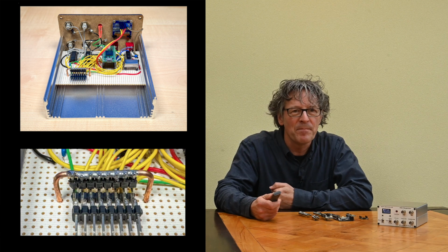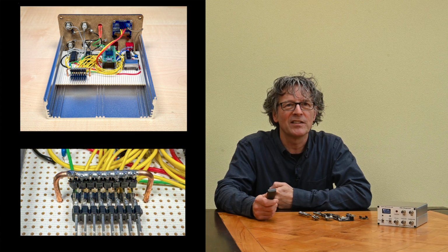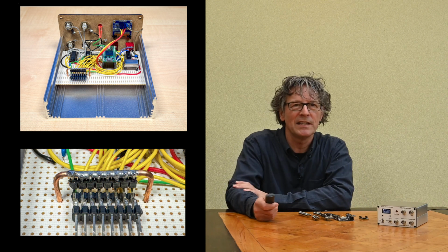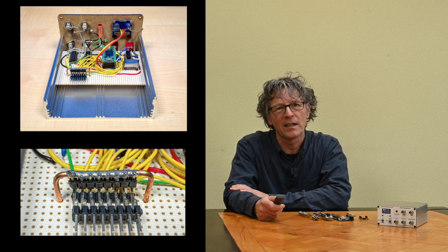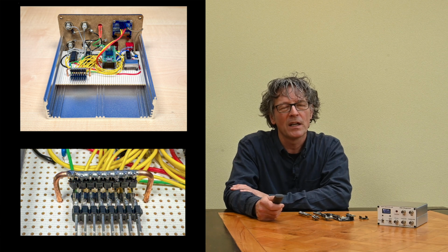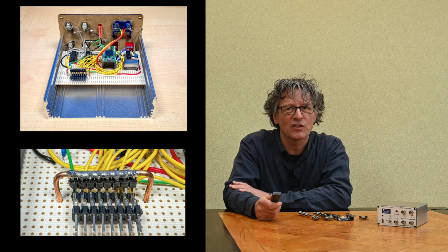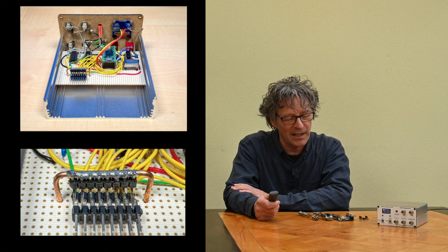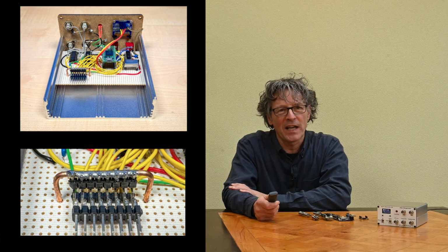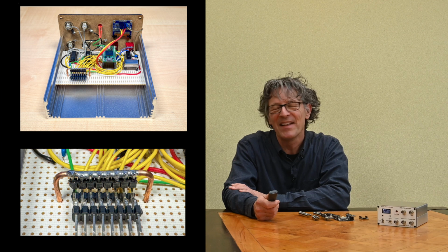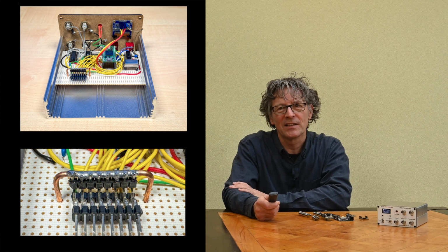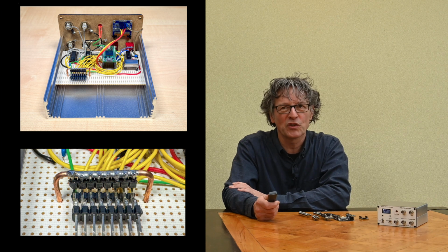Let's make it a little bit bigger here. That additional header is a debug header. It can be used to connect the prototype right away to the digital lines of a digital oscilloscope, to do some further analysis of how the code is running internally. The reason why I built a connector like this, I mean, it's a bit brutal, is that I wanted it to be a very robust type of thing rather than elegant. I wanted to be able to directly connect the digital port interface to an oscilloscope without having to put all the wires there one by one.